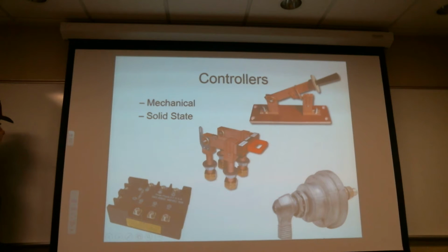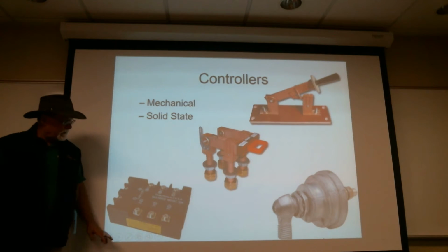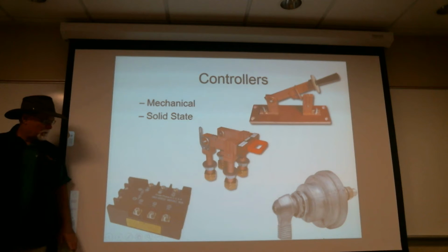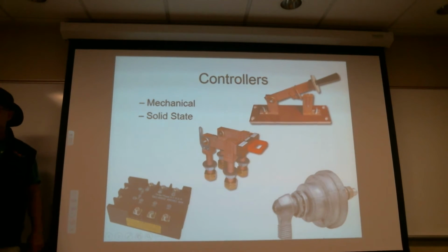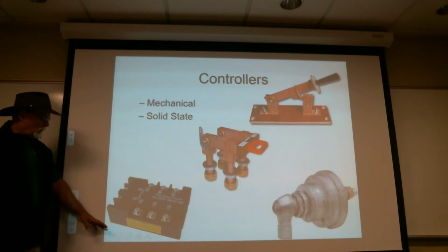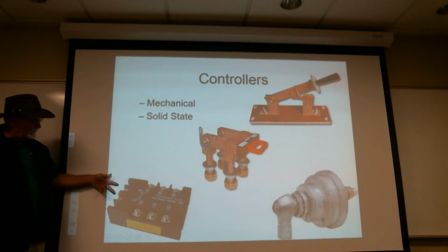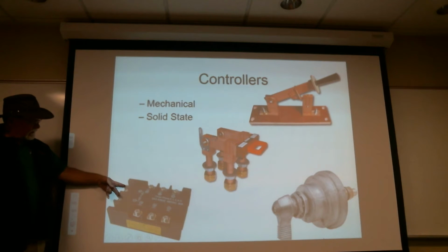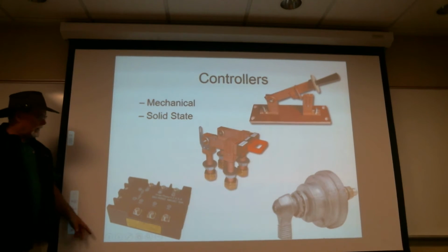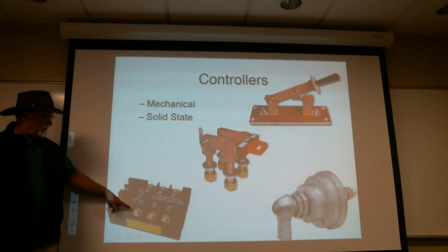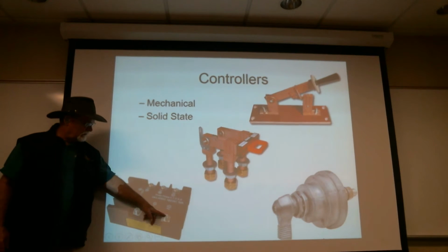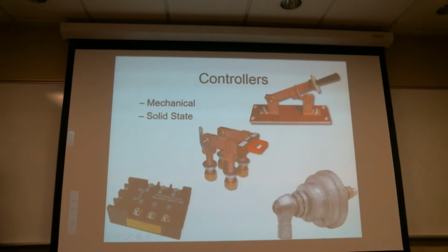This one here is actually kind of handy. It may or may not be a mechanical relay. It's probably a solid state one, and this tells you everything it does. It's actually 3 individual switches for circuit A, B, and C, 3-phase. So instead of that big circuit breaker, let's say this is sitting in the 3-phase compressor. I've got a relay that comes on, either solid state or otherwise. All I need to do is feed 32 volts, and it looks to me like it's probably solid state because it's saying plus here and minus there. So somehow this is polarized. If I apply 32 volts across here, that's going to connect small a to big A, small b to big B, and small c to big C in a sealed environment.